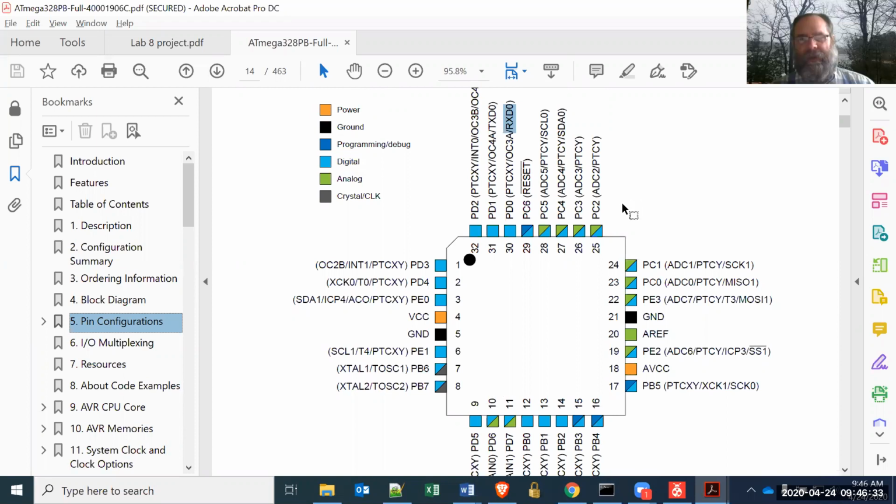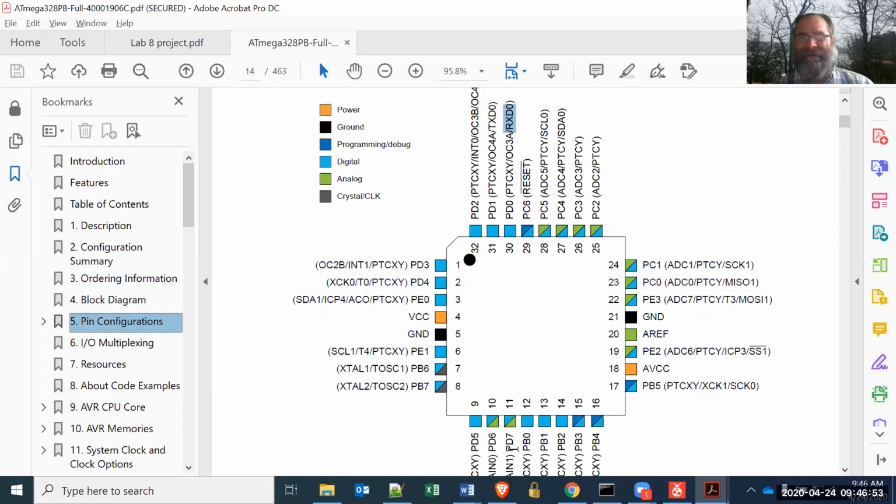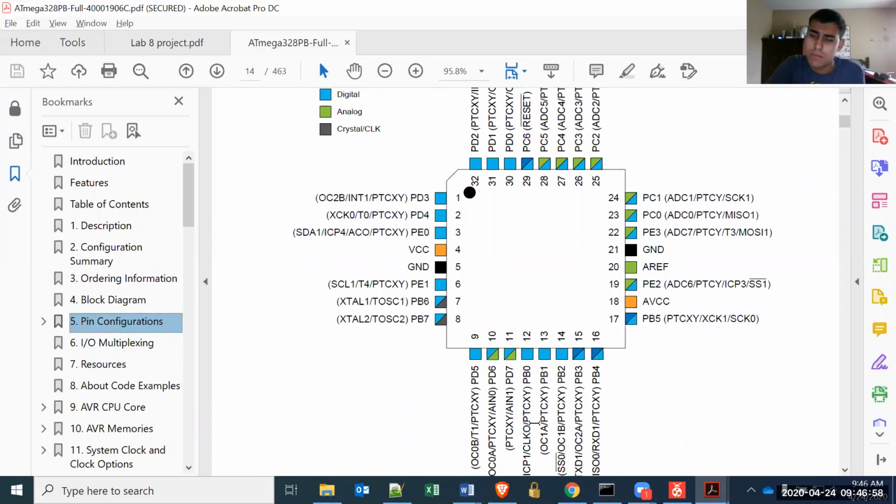Okay, well, keep in mind with UART0, it's already got a MAX232 chip, I think, or some kind of MAX232 chip, which goes to the USB and to your computer. UART1 isn't really connected to the outside world through a USB cable. So conceivably, if you had a socket, you could put a MAX232 on it. You'd need another USB cable to go to your computer.